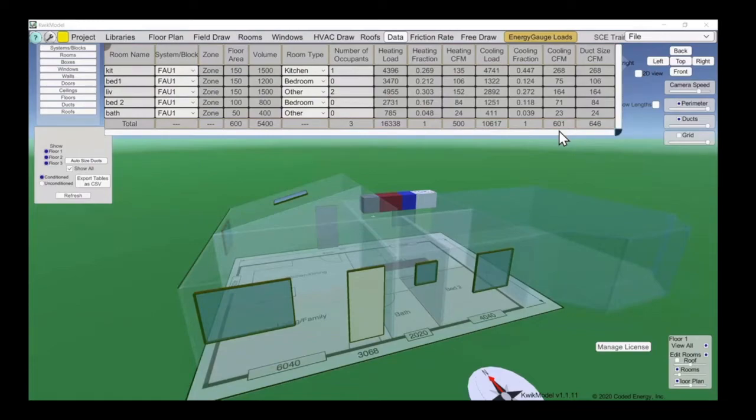The other thing we want to do is make sure that 601 CFM goes to each room proportional to its load, and that was all these calculations up here. So as long as we can get at least 268 to this room, 75 to this room, 164, 71, et cetera, and at least a total of 601, we can be confident that that house is going to be at a relatively even temperature throughout.